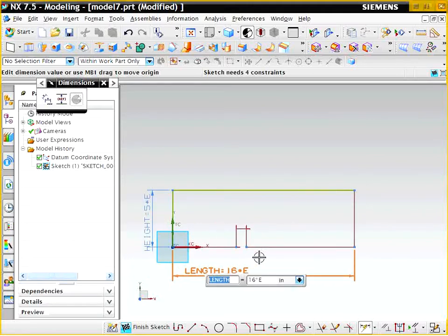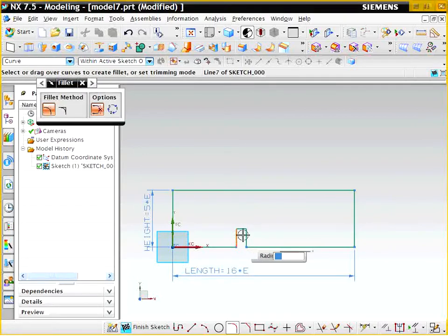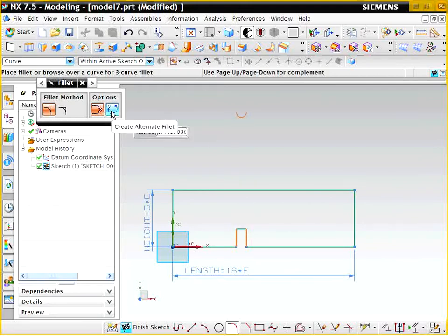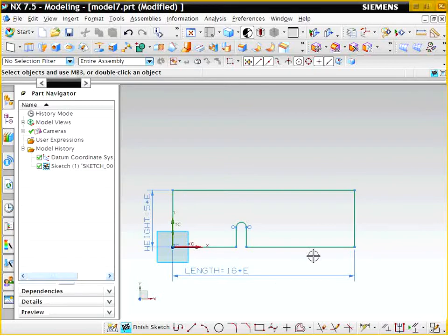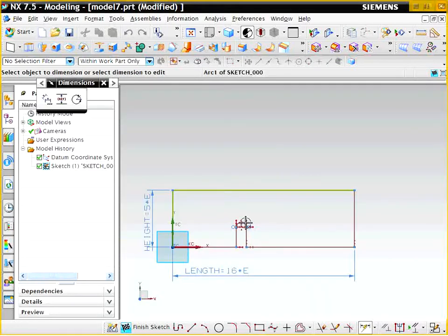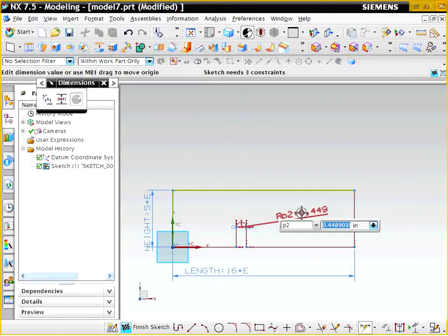Let's look at also the radius here. I'm going to go ahead and chamfer this edge just like we've done before in the past. I'm going to make sure I have these two buttons selected when I chamfer this. And there you see the little chamfer that is going to come out now. Okay, so I'm going to dimensionalize some of these parts. I'm going to say that this radius is supposed to be 0.5 times E. Okay, and I'll call this one radius 1.